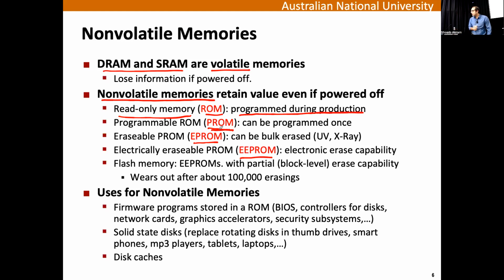You cannot program it again. EPROM, you need special equipment, and electronic erase capability is where you can actually put that on your integrated circuit and you can erase it using software. And then there is flash memory that we'll look at in detail. You can actually partially erase certain blocks.